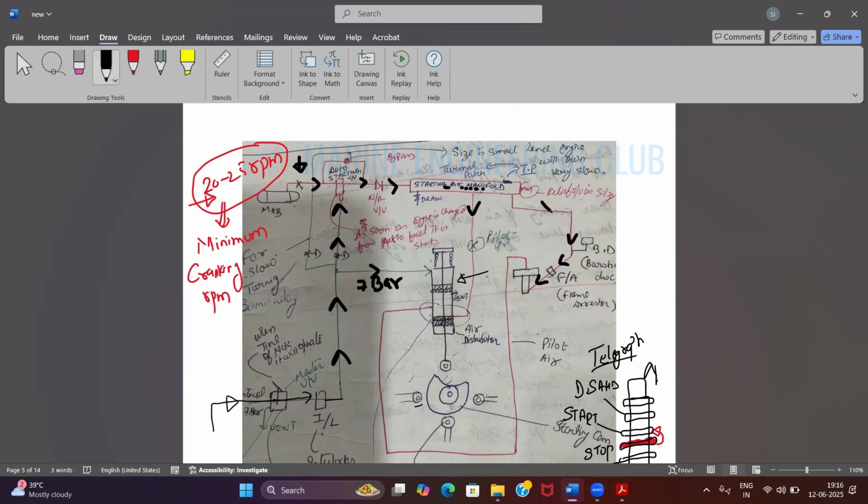All the units are getting this air, but this 7 bar air, when it comes, will try to push my piston downward against the spring pressure. It will try to push the distributor of my air distributor down. But only that particular unit will come down whose roller is on the negative part of the cam. Others will stay in their position itself. It cannot go by breaking the cam. Agreed. So only number 1 unit can come down, right?